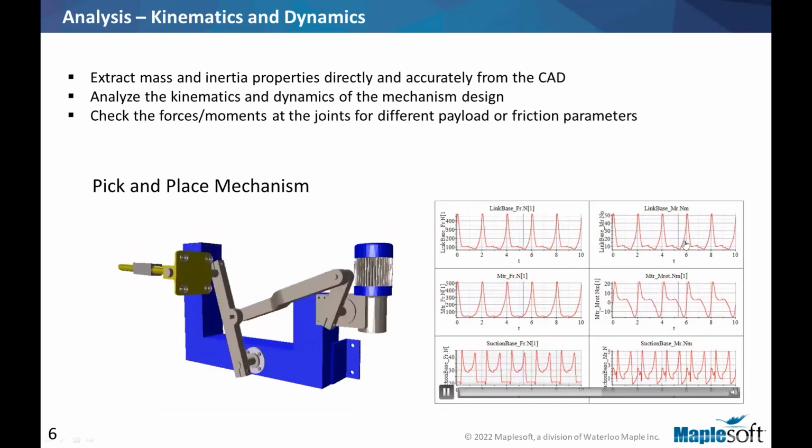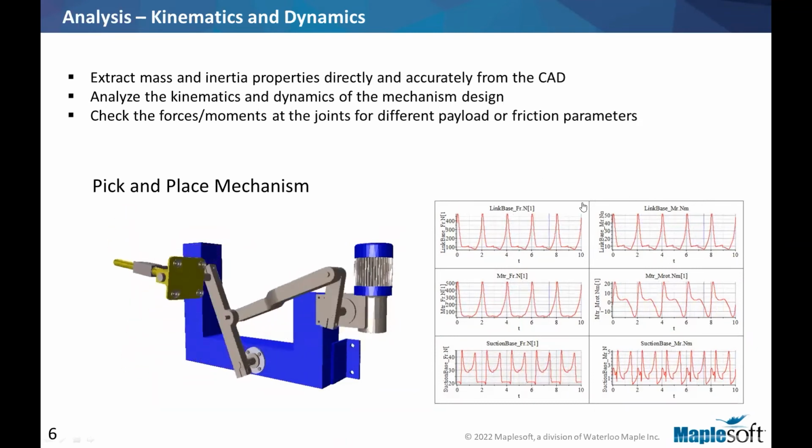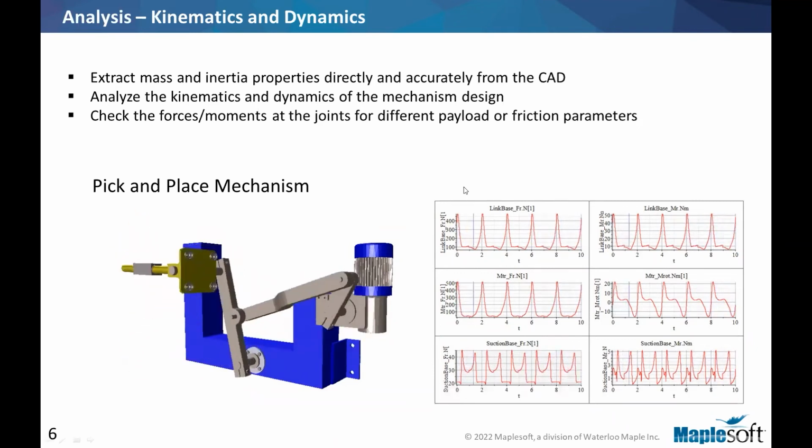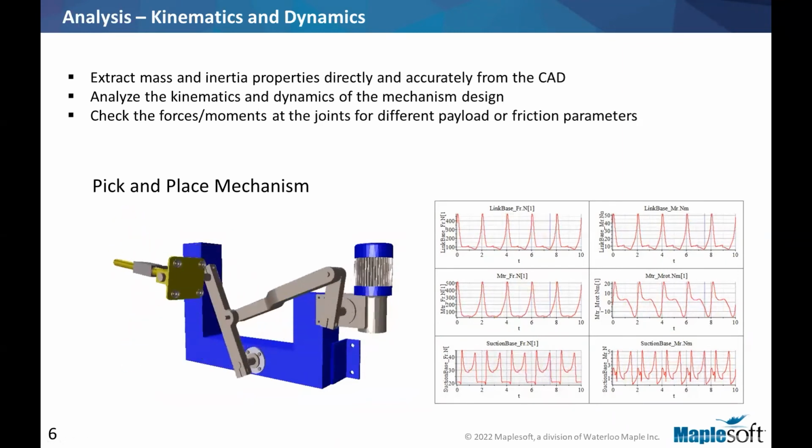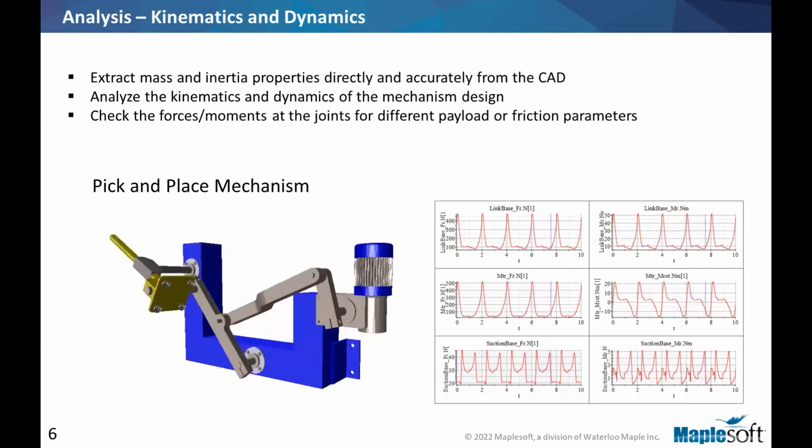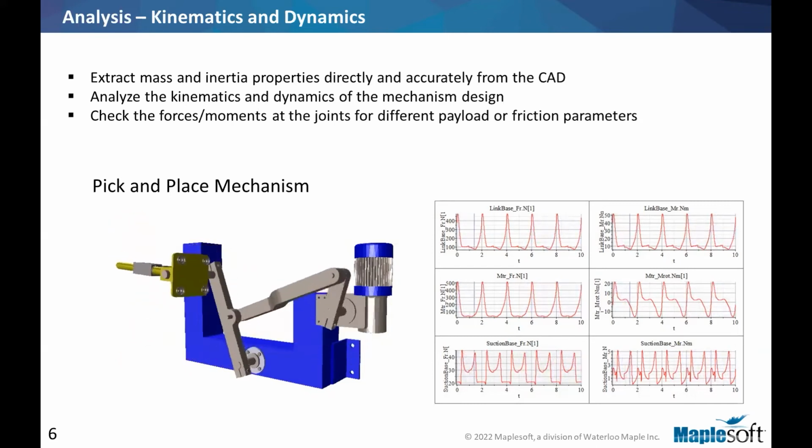And you can actually see this on the side here. So as my simulation is moving along in time, I have this vertical blue bar that is reporting to me where I'm at in time, and I can see the value for the forces and the moments. So if you're looking at doing things like motor sizing, or if you have a specific motor on your system and you want to see how fast you could run it before you hit those upper limits, this is something that you can investigate with MapleSim quite easily.